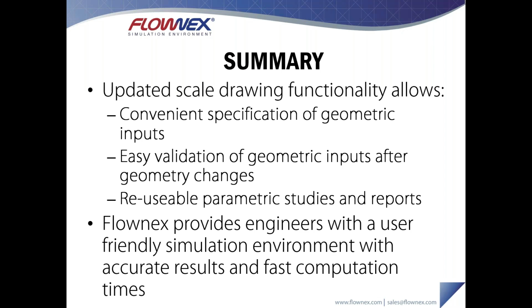These measurement inputs also provide an easy way to validate the geometric inputs of your model after a geometry change. So like the second scenario where I changed the image in the background and then moved the location of the measurements, you can do this in a geometry change inside of a system. Perhaps the size of a labyrinth seal changes, or the radial location of a labyrinth seal changes, or the profile of a rotor stator changes, or something like that. All of this information can be captured in drawings. The drawings can be updated, and then the geometric inputs will be updated automatically.